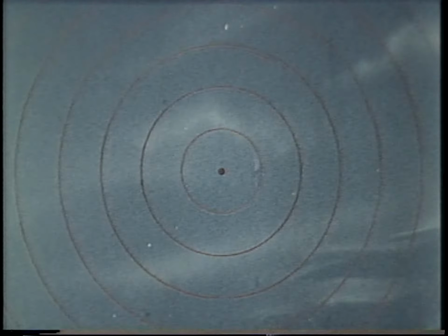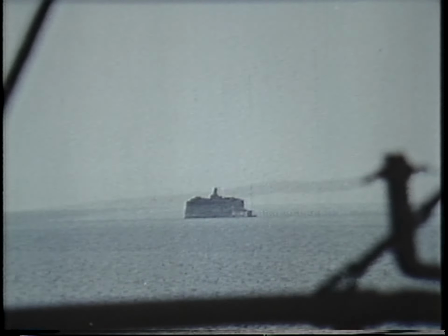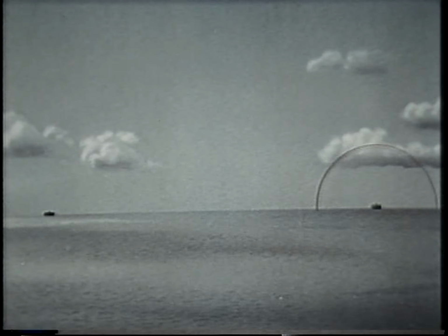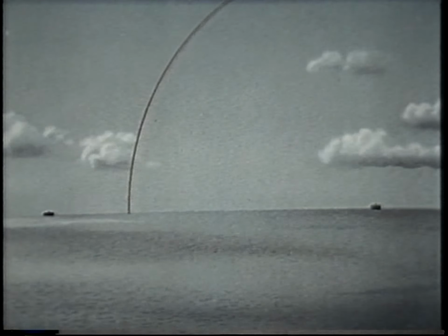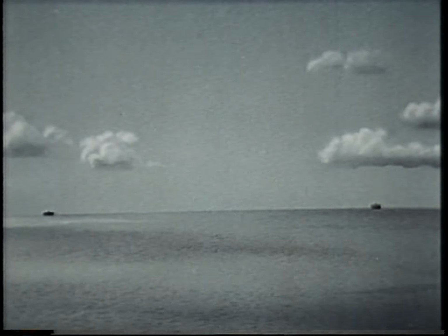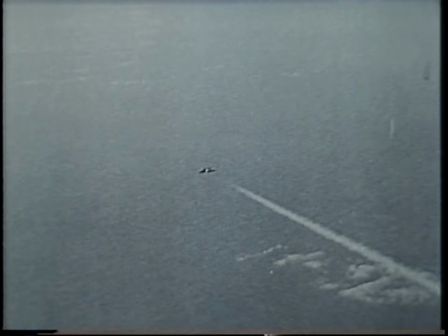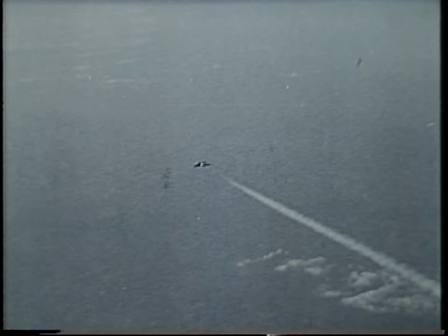Not all pressure waves are audible, but all small disturbances, audible or not, travel outward at the speed of sound. Watch this explosion, a mile away. Its sound takes 5 seconds to reach us. At sea level, sound travels at about 760 miles an hour. But the speed depends on the temperature of the air, which drops as we climb upward. In the stratosphere, which begins at about 36,000 feet, the speed of sound is only about 660 miles an hour because of the lower temperature.